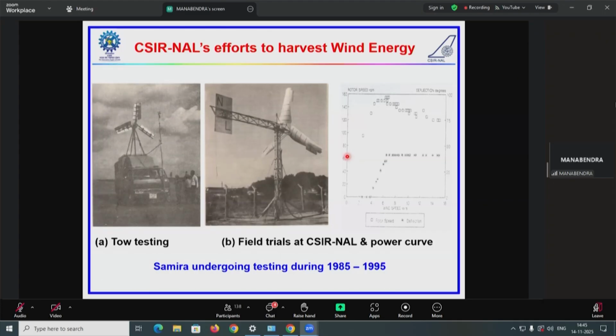Also, we experimented with various configurations, and one of the approaches is to anthropogenically generate the wind by mounting a prototype over a van, with all the instruments housed inside the van, and then the van is run at a predefined vehicle speed so as to artificially generate the wind. This is an interim way of testing a wind turbine between a wind tunnel and the actual field trials.